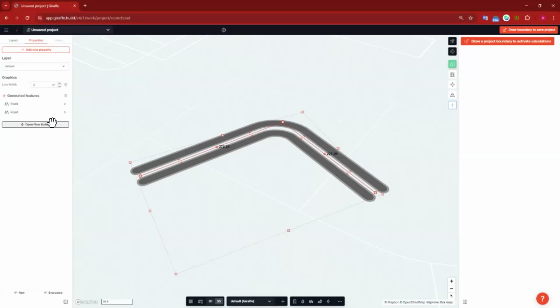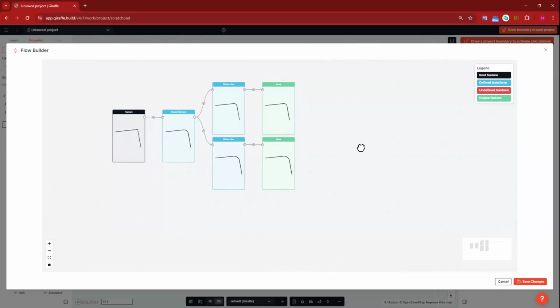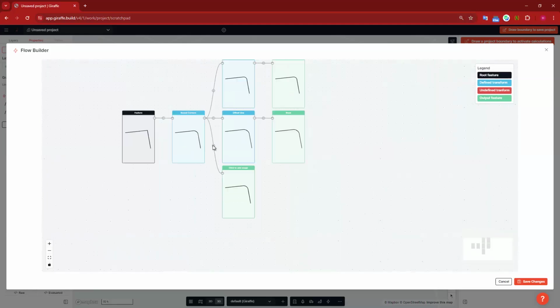And then, like I was mentioning, maybe we also want to add some trees down the center. That would mean that we need to add yet another output. So here we've got these two outputs, they're both road. I want to add another output that's going to be an array of trees like we looked at the beginning. So what I'm doing is clicking this split button. So rather than the copy split button, this one just adds another whole new branch, and it gives me a new output.